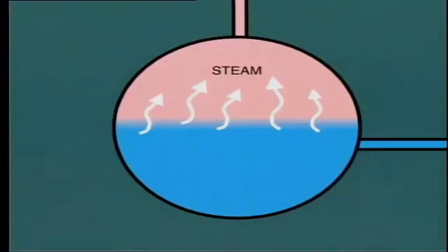First, the problem of scale. As much as we try to provide perfectly pure water to the boiler, it is inevitable that some small quantity of contaminants do get through and concentrate in the boiler water as more and more steam is evaporated. Remember, as water evaporates into steam, the solids contained in the water remain behind, and this concentration increases as more and more steam evaporates. This is the situation which occurs in the boiler.